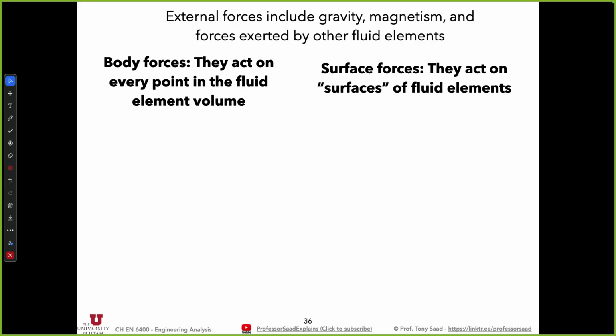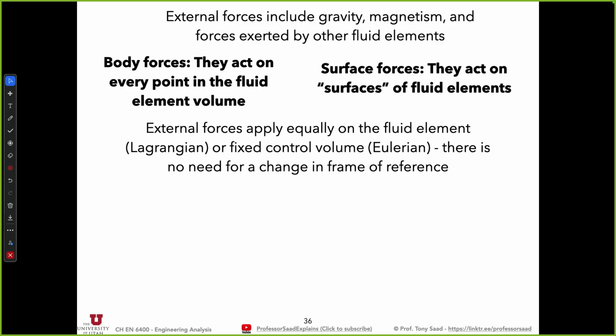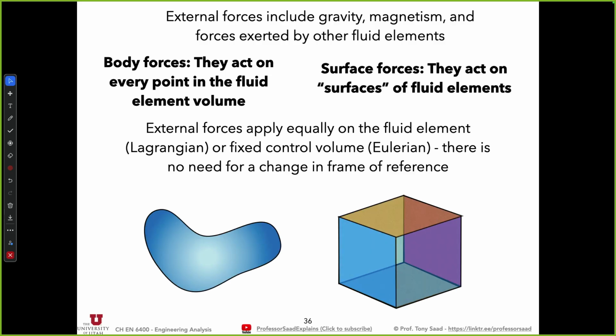So whenever a surface is present, surface forces will start acting. Body forces, whenever a volume is present, body forces are going to act on it. Now, these apply equally. There's no Lagrangian or Eulerian form of external forces because they act the same way on a fluid element or a fixed control volume. They look the same. There's no frame of reference change, thankfully. So there's no Reynolds Transport Theorem equivalent, okay?